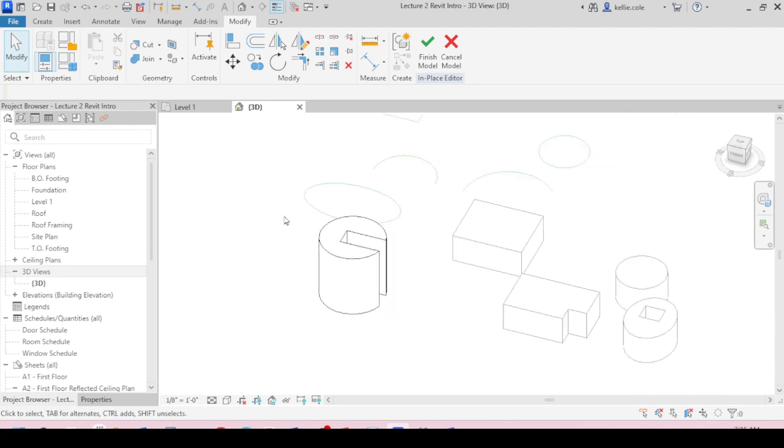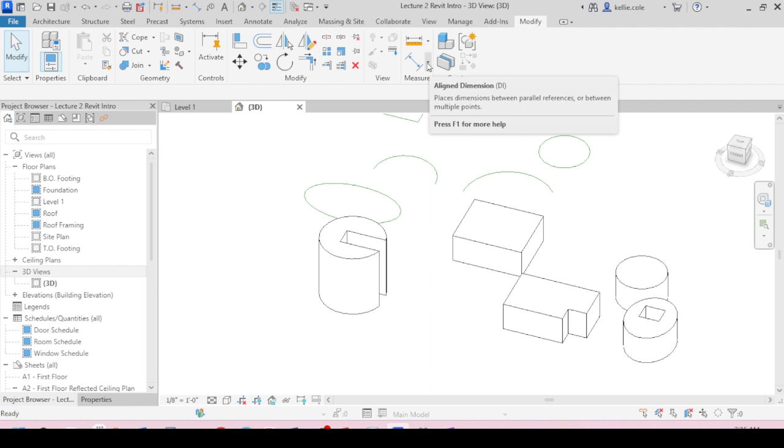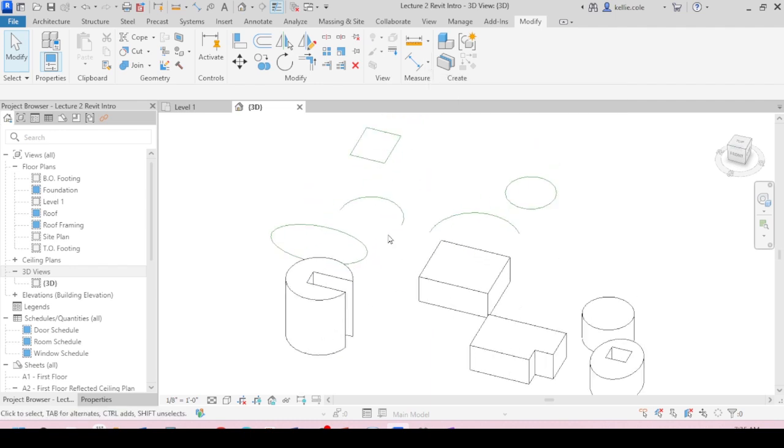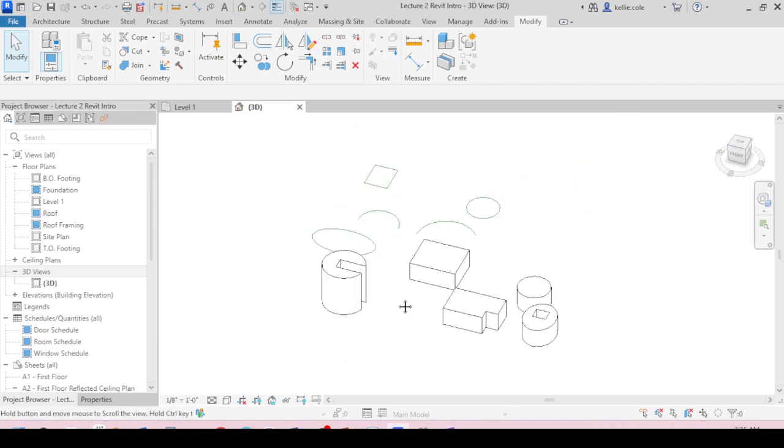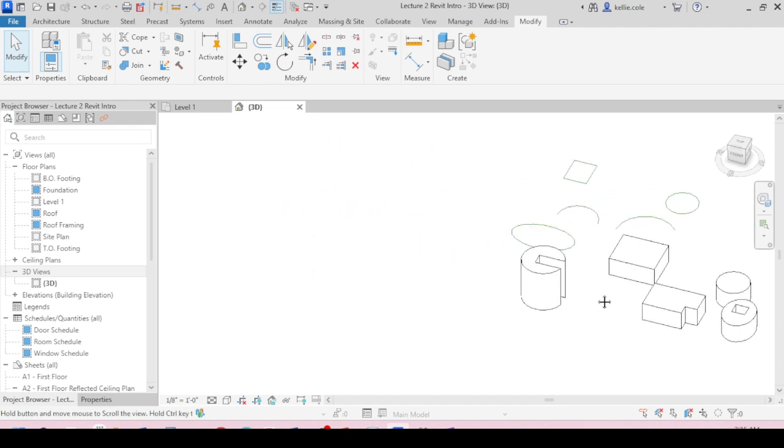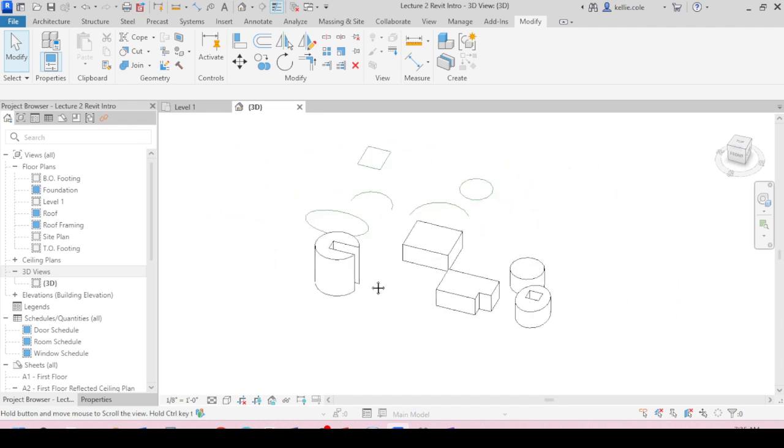Let's rotate around our objects now. Let's hit the check mark first. And I want you to scroll with your mouse in and out. If you want to move left and right, push down the Control, scroll, and move your cursor again, left and right.